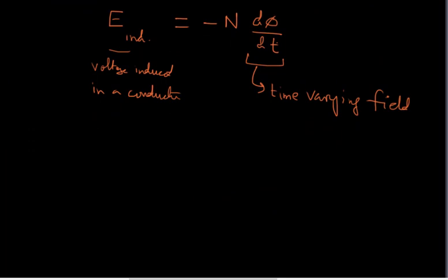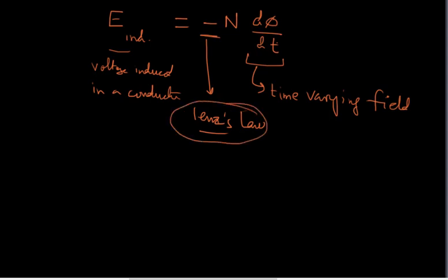One important thing is, what is this negative sign doing? This negative sign is due to Lenz's law. When the magnetic field from the permanent magnet is coming to the coil, the coil itself is going to produce a magnetic field which would oppose the incoming magnetic field. This is a slight detail into this topic. We would talk about this detail when we learn transformers, and I would be talking about Lenz's law in much more depth in the topic of transformers. Until then, you need to understand that this negative sign is due to Lenz's law, and it tells you that the reaction of the coil is going to produce a magnetic field in the opposite direction. That reaction magnetic field is not in this equation. This equation only talks about the action part of this phenomenon, the law of electromagnetic induction.